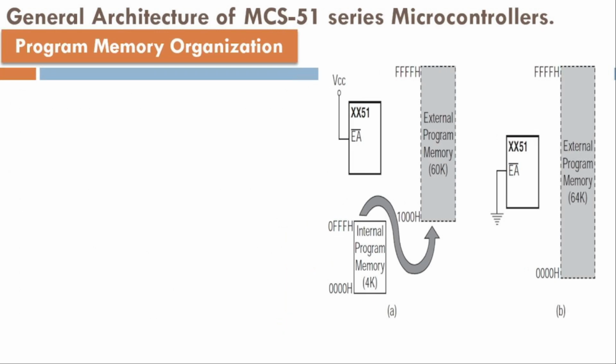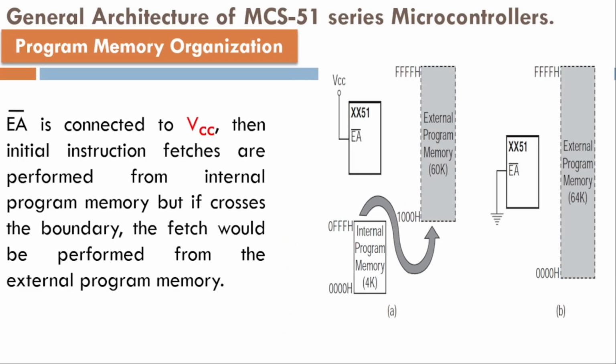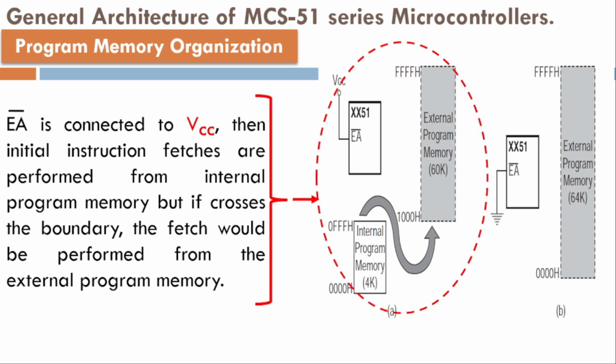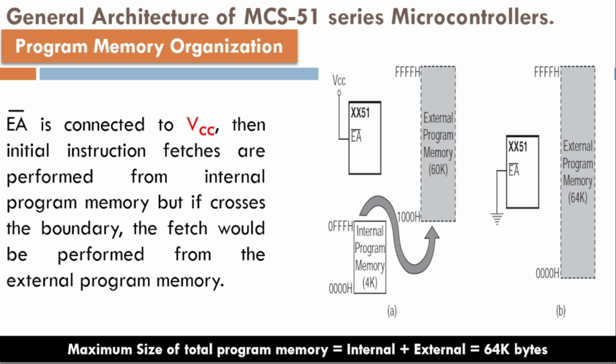When EA, external access, is linked to the supply voltage VCC, the initial instruction fetches occur from the internal program memory. However, if the instruction boundary is exceeded, the fetch will be conducted from the external program memory, as illustrated in the accompanying figure.